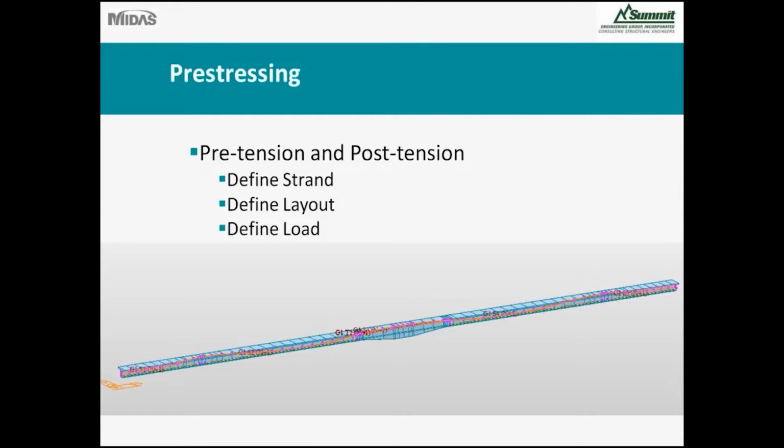For the pre-stressing, we had pre-tensioning in each girder segment and also post-tensioning. And to put that in MIDAS, we define the strand, define the PT layout, and then define the load.